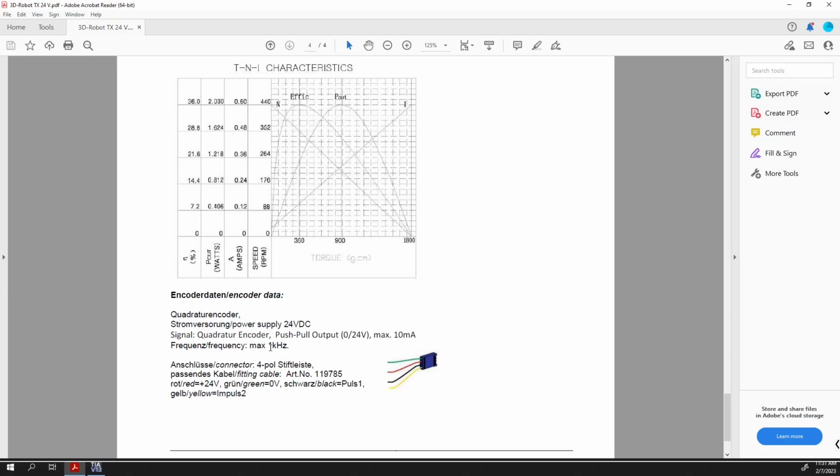And what happens is there's a little interrupt that gets thrown. So every time that input goes high when we have a high-speed counter enabled, the interrupt gets flagged, and the PLC kind of pauses what it's doing, counts, and then goes back to what it was doing again. So really nice in that aspect.